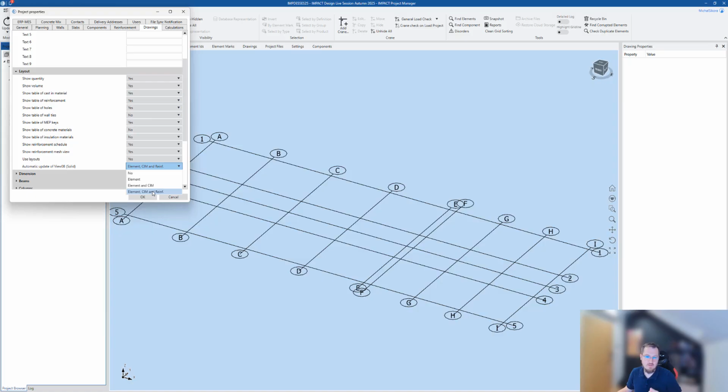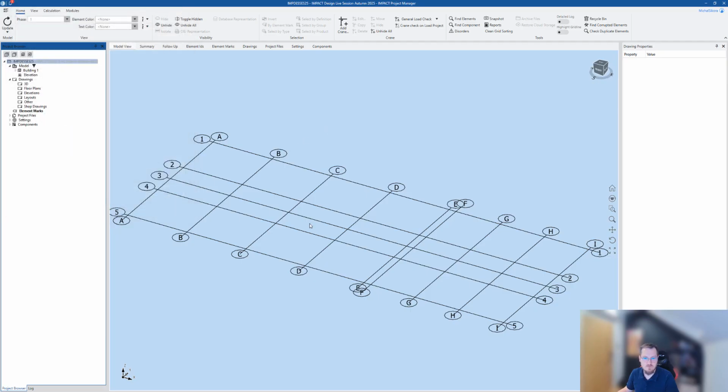Basically, you need to have a drawing of the element generated and a solid view of that element visible. And if there's reinforcement and casting materials in that solid view, then you will get the OBJ files to get the reinforcement in Project Manager. And that's the option here. So when you create drawings, both the casting materials and reinforcement will be automatically applied to a solid.